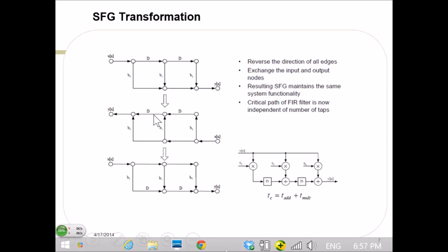Isn't that another way of saying that if you have a minimum delay per filter or a maximum delay per filter, they're related by the coefficients flipping? Yes, it all depends on how the filter is structured. It's the same equation, but the internal computations are done in a different sequence. Here, for instance, we are essentially buffering the inputs.